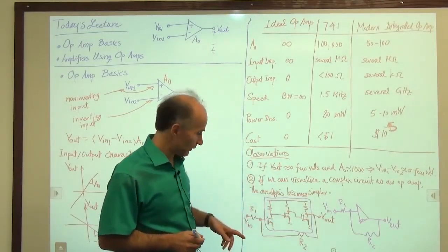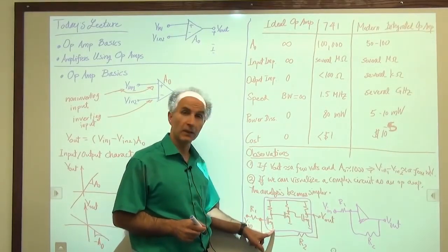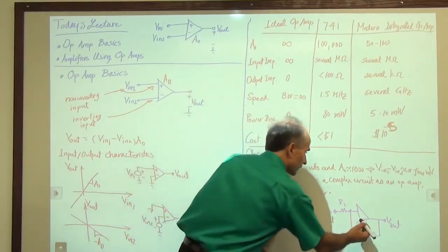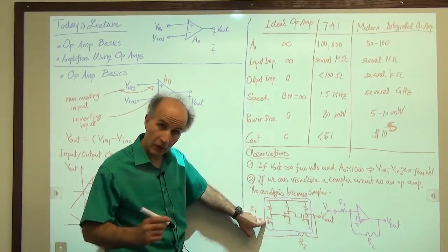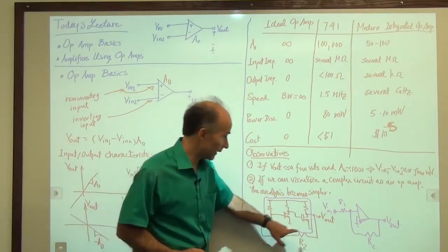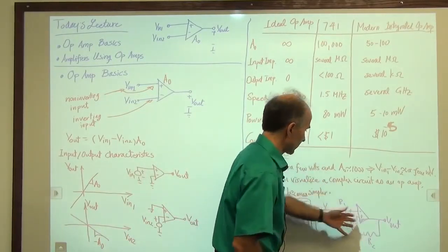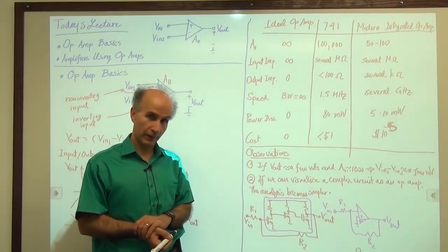Well, that's easy. What really happens is that this circuit has actually 1 input here, 1 input here. One is grounded, right? So you can say that the other input is grounded. After all, this gate voltage is measured with respect to ground. So I can just assume there's a ground here and say, well, this is just a simple op-amp based amplifier, and I can quickly answer the question.